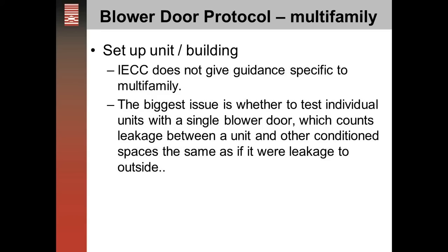If you're testing unit by unit, all of that leakage is going to be counted as leakage to the outside. So you'll need to meet that 3 air changes per hour in the 2012 code for each unit by unit. And if that works, you could certainly test it that way.